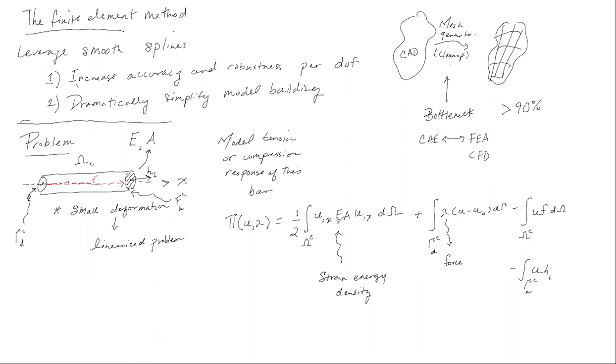We have the energy consumed by internal deformation, the strain energy. And so this whole thing, this kind of potential energy, pi, should be equal to some constant. Okay. So this is a very common starting point in structural mechanics, is you postulate some energy. And then we're going to start with this energy and derive a finite element method from this.